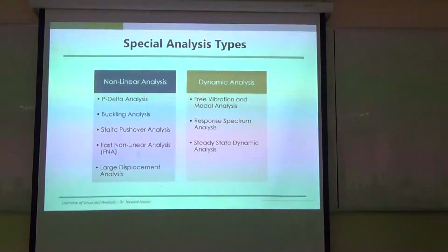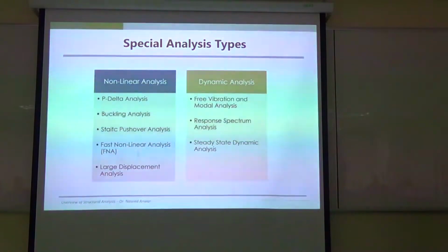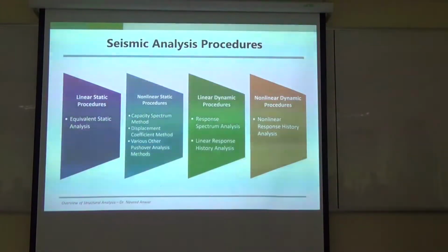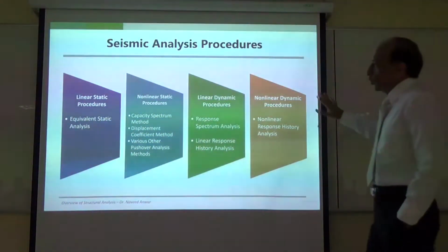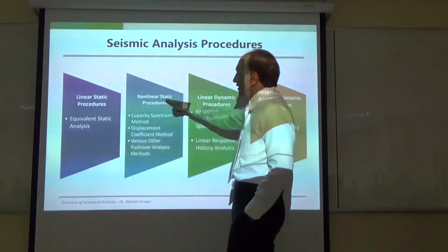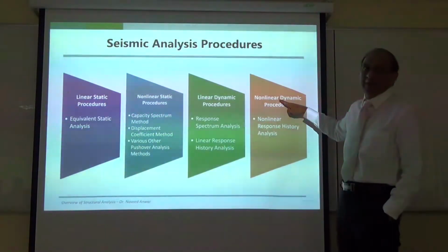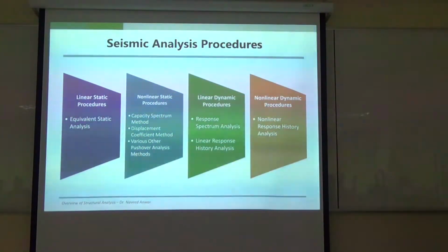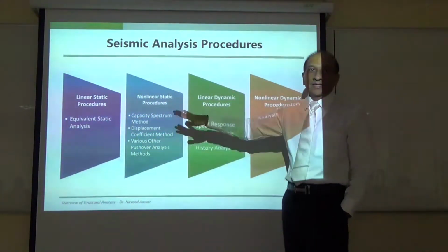Right? Similarly, many types of analysis can be done. So the trick is to learn these analysis options and see what data is needed, how to carry them out, how to interpret the results, and how to use them in real situations. So for the same model, more or less, you can run many types of analysis. Seismic analysis procedures have four main categories: linear static procedures, nonlinear static procedures, linear dynamic procedures, and nonlinear dynamic procedures. So you can do four levels of seismic analysis, earthquake analysis, and we will talk a little bit more about that. Not all of them can be done in this class, that is impossible, but at least we will introduce a little bit.